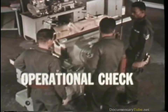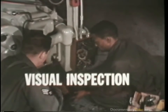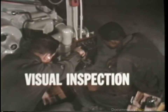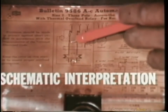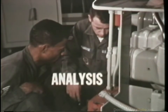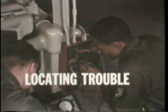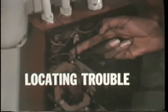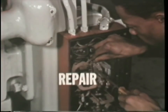Make an operational check of the circuit. Conduct a thorough visual inspection. Study the schematic diagram if it is available. Analyze the information that has been obtained. Locate the actual position of the trouble. Perform the repair.